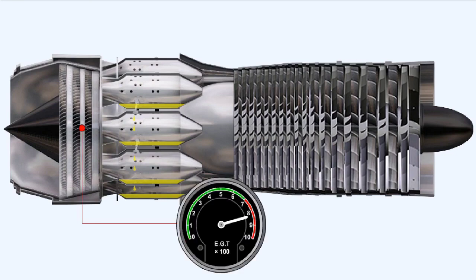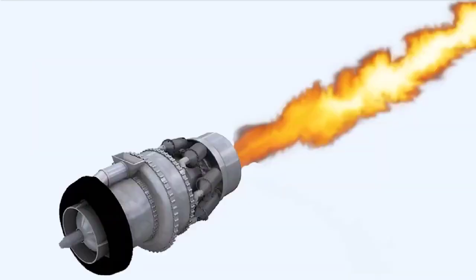If that fuel is not removed before the next attempt to start, and if that attempt is successful, the result will be a combination of excessively high gas temperatures in the turbine region and torching, which is the name for a very long, very hot, and very dangerous jet of flame issuing from the rear of the engine.